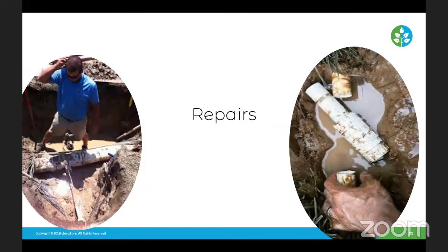Okay, so I have another one. It says, I have a leak from the pressure release portion, forgot what you called it, of the valve. Is this normal? The pressure release portion. Okay, so the bleed screw or the external bleed screw is what I'm thinking. Yeah, that should not be leaking constantly.